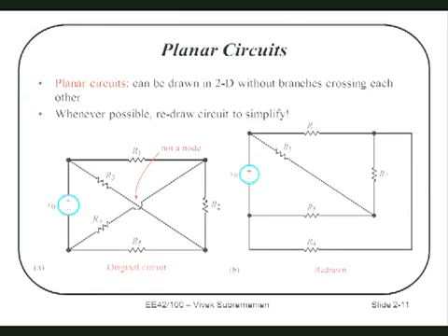So this is the first rule now of analyzing circuits. We've got our first rule. Our first rule is make your life easier. Usually, try to redraw the circuit such that you don't have to deal with these weird things. It makes it easier for you to identify loops and so on and so forth. And so it's usually easier to start by just redrawing your circuits like this.